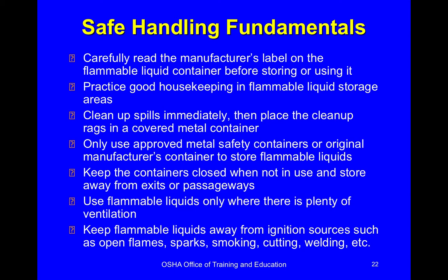When it comes to safe handling, you've got to know what chemical you have, read the labels, and look at the safety data sheet so you understand what you're dealing with. Good housekeeping is very important. If you ever have any spills, clean them up immediately. Remember, you're probably dealing with ignitable vapor. You need to clean the source up right away.